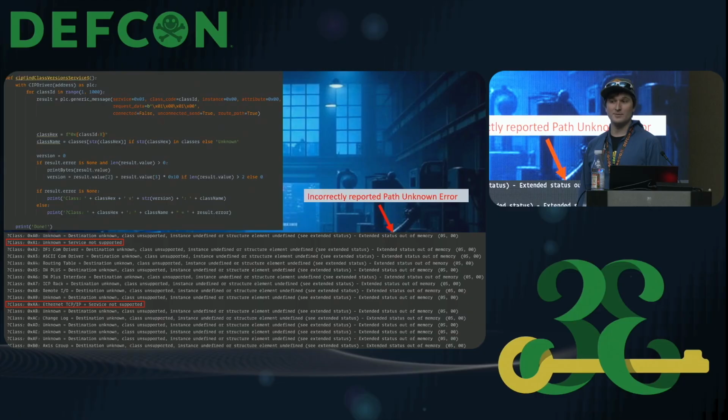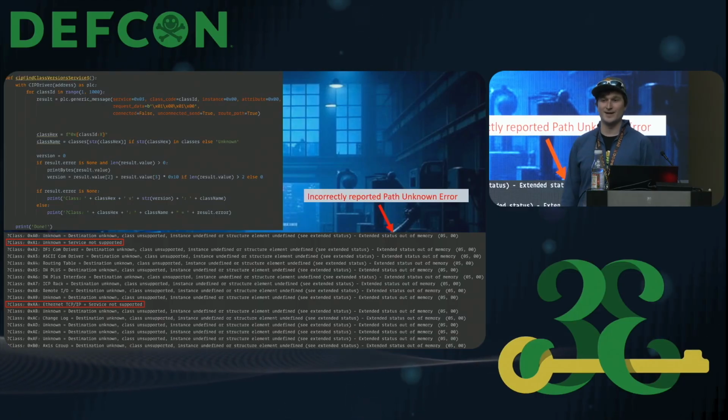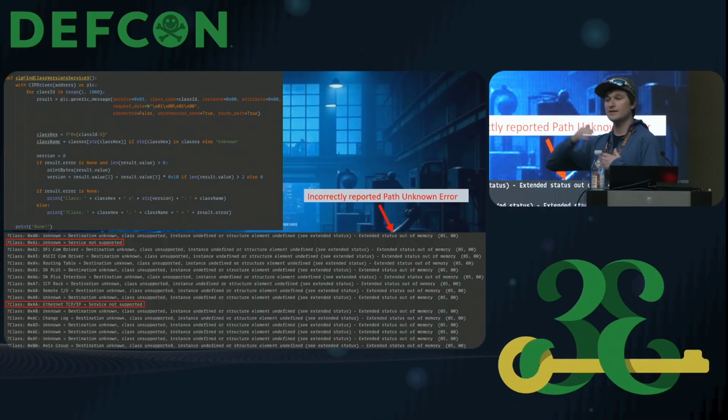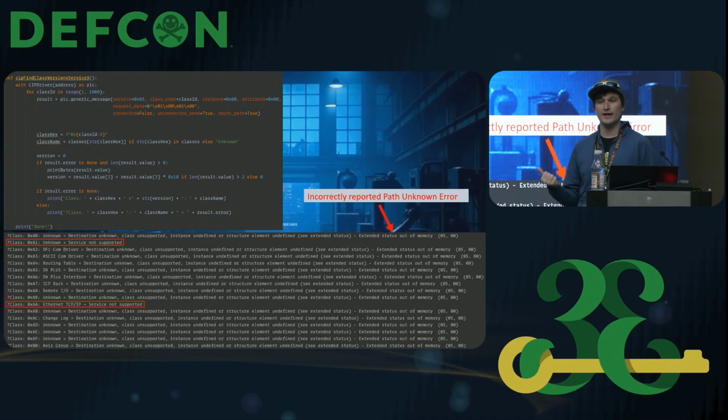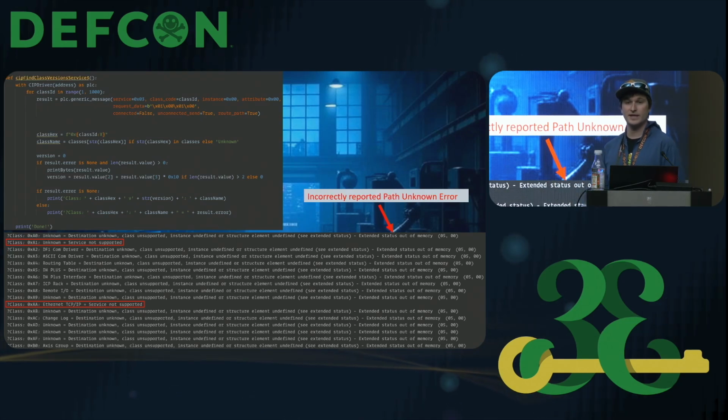Now, granted, I'm talking to it on an Ethernet-based network, it better have that object. But the fact that it's exposing that object to me on the network means I can now access that object, I can query that object, and I can control that object. Because as part of the CIP specification, the TCP object allows me to remotely set the IP address of the device, change its gateway, change its subnet mask, without requiring any authentication mechanism. You could modify this script right here to go change the IP address of this device just like that, and the device would have a new IP address.